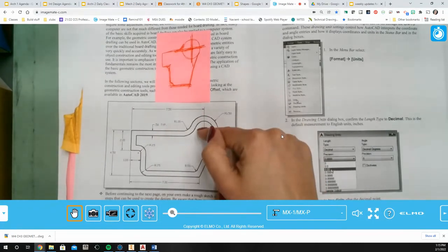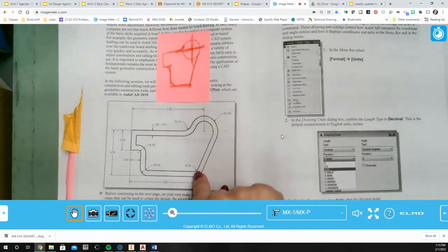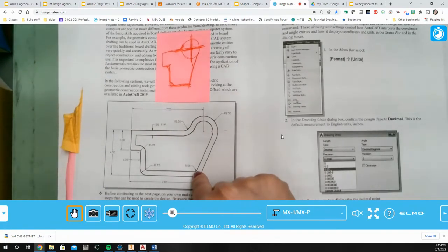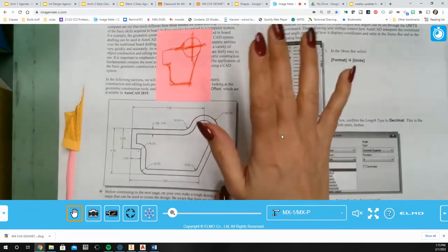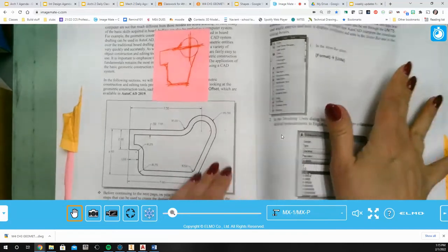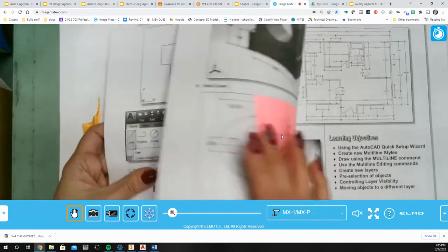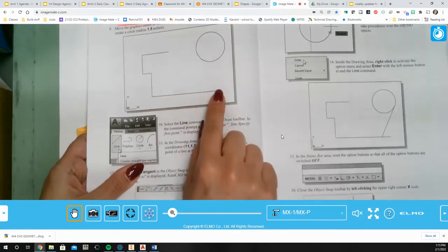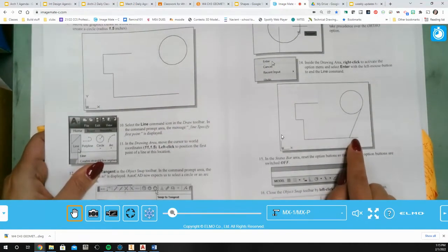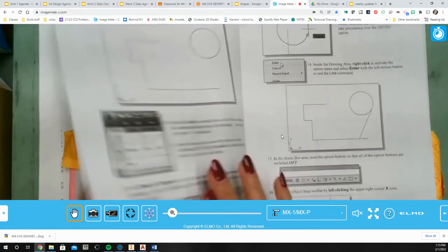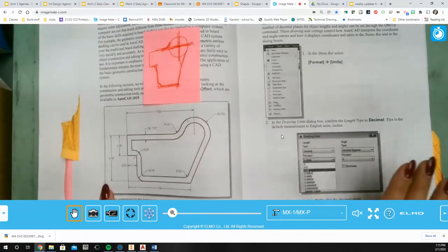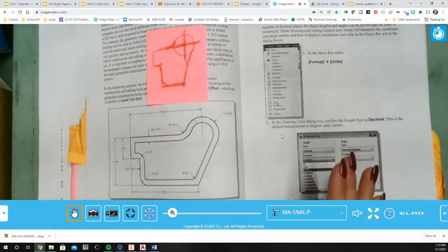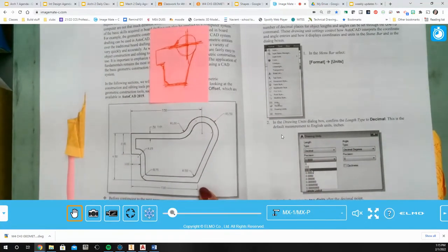So once I've offset it to the inside, then I'll come in and I'll use my fillet command to do this. So once I go to fillet, remember you have to go all the way to the bottom right away, click on radius, change the radius to 0.5, and then click those two lines, and then you should be good to go. You don't have to put any of these dimensions in for me, and the book does a pretty good job of walking you through. I would say that there's a part right here where it gets a little confusing. You can see over here they got this little extra piece of line sticking out. So either draw it according to what you see here, or you can follow the guides in here. As long as the end product looks exactly like this, you're okay.